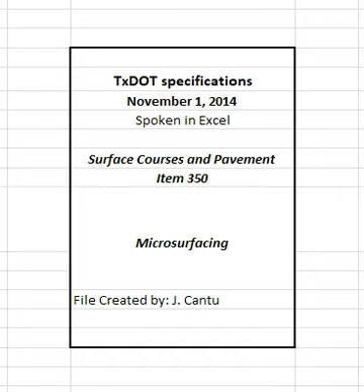4.1 Mixture Design. Provide a mixture design meeting the proportions shown in Table 3 and the requirements shown in Table 4. Provide the engineer with representative samples of all component materials for verification of the mix design, unless otherwise directed. The construction division will verify the mixture design to ensure it meets the minimum requirements for wet track abrasion value listed in Table 4.